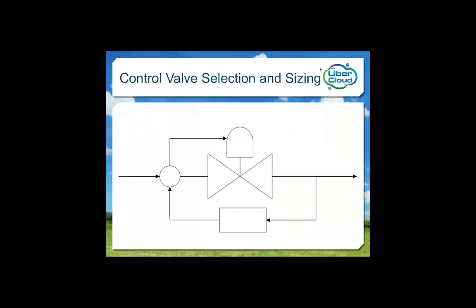This schematic describes a simplified common installation of a control valve. Multiple parameters can be measured, fed back through a data processing algorithm to a controller that also knows the conditions upstream. The controller will then send a signal to the valve actuator, causing the valve to change its restriction to maintain a desired condition downstream.